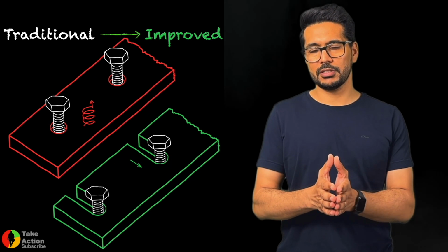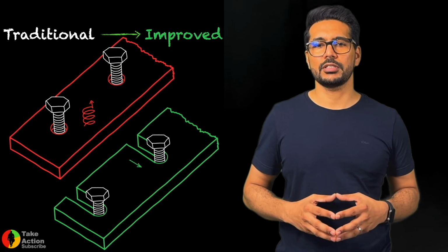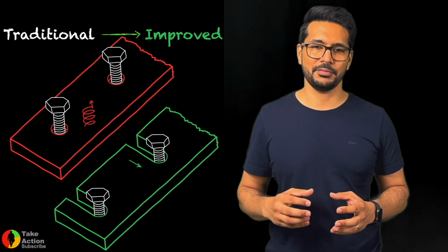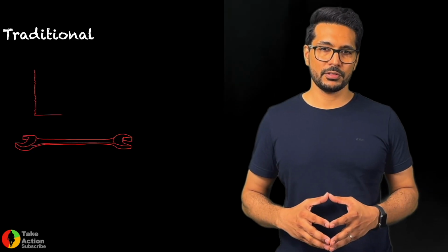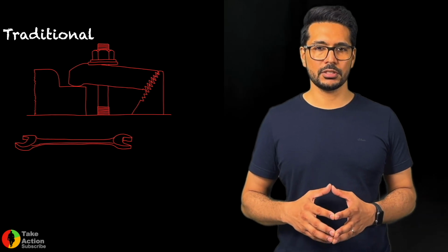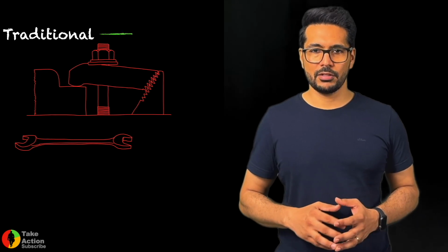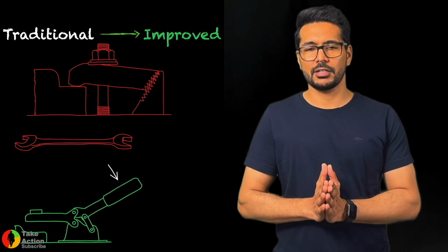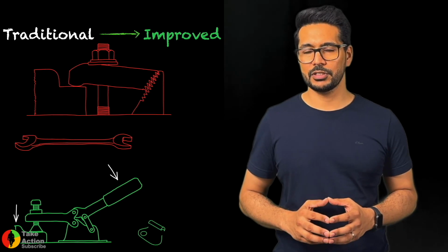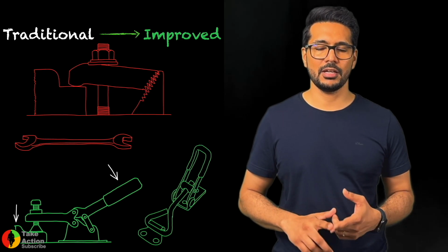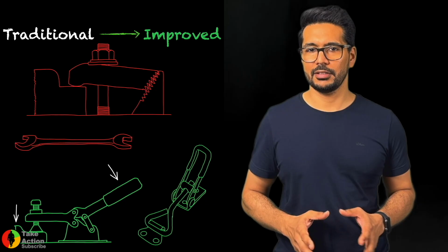So these are the ways in which you can speed up the whole replacement of the parts during the setup time. So in case the setup time involves any fastening or any clamps with bolts which requires a spanner or other tools, that you can also check. There are in the market a variety of clamps which don't need any type of spanner, Allen key or anything like that.